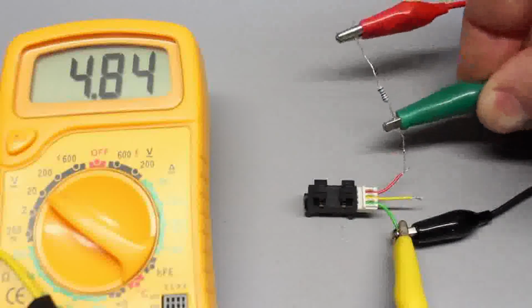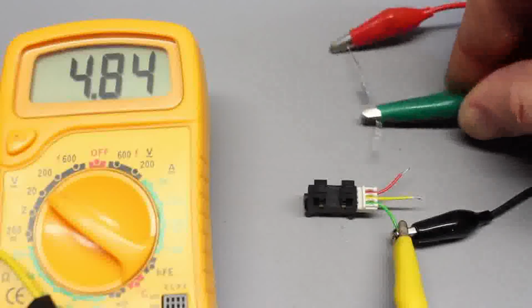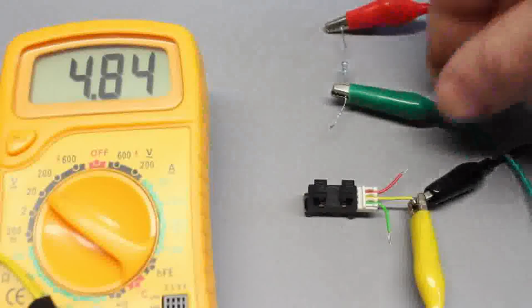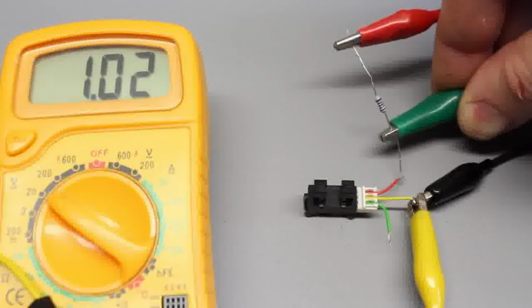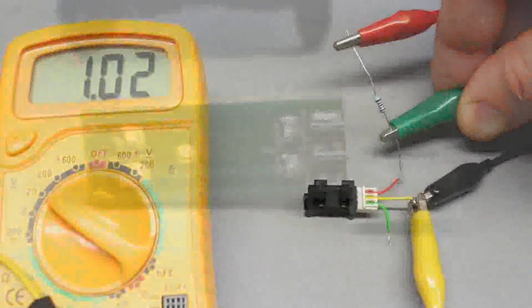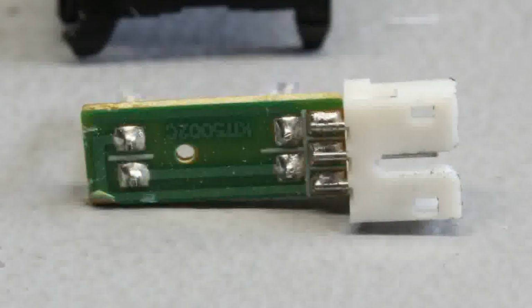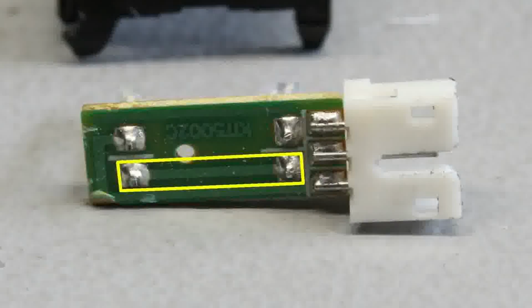Once again there is only one configuration, with the LED being forward biased and so a voltage reading clearly below 5V. With that, the ground pin and the LED side are identified. At the bottom of this device you can clearly see that the ground pin of the LED side is joined with the transistor side.